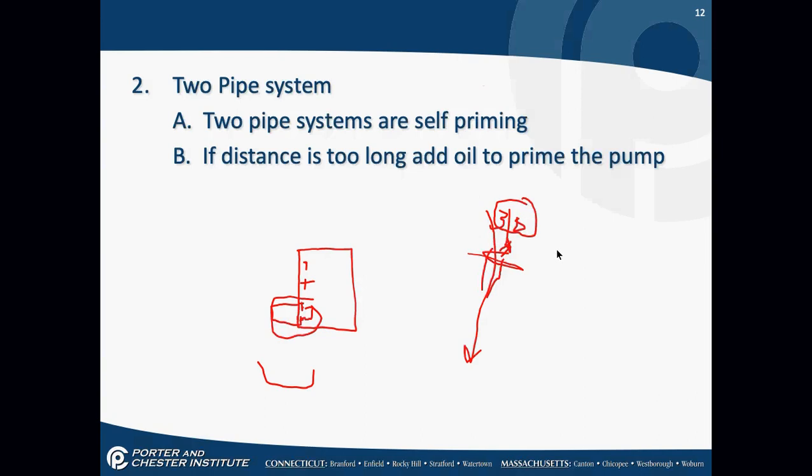Air coming through the oil burner will turn that oil into sort of a milky, very small, foamy type of bubble. Once there's no more air in it, I have a red stream of steady, clear, reddish oil. There's a big difference in the air in the oil and no air in the oil. If you have any type of foam coming out of here, foamy bubbles, you still have air in that oil